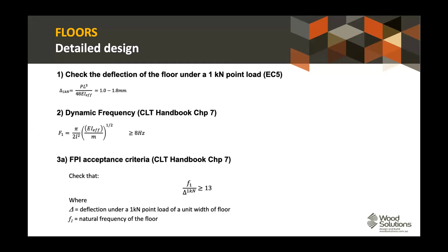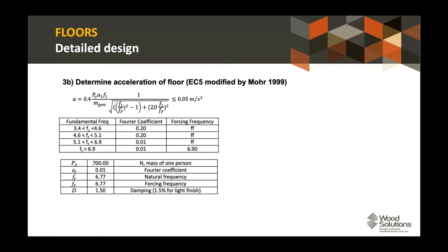And to be perfectly honest, if I was pushing a floor hard to try and make it as efficient as possible, I might step through these checks in order, but I would always do all of them rather than missing off the final check, which is this acceleration check. It's the acceleration we perceive, and the acceleration that, being a lightweight floor, is something it's particularly susceptible to.